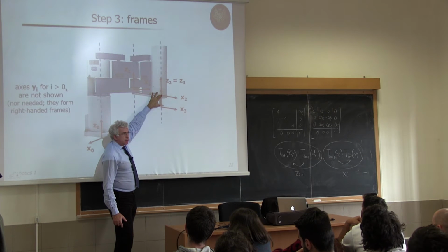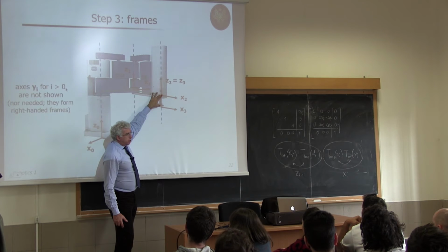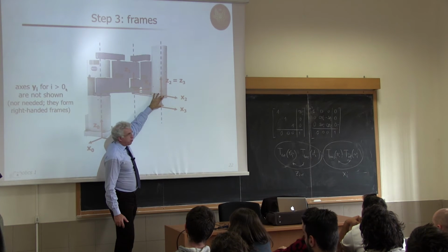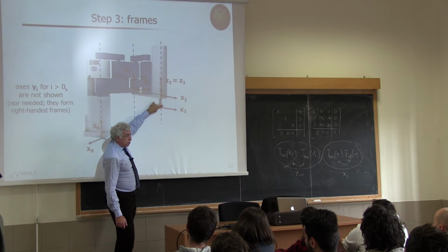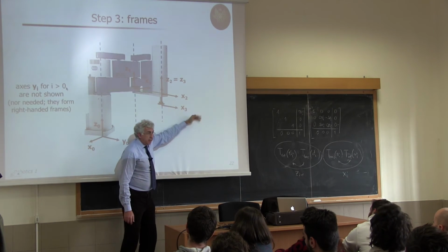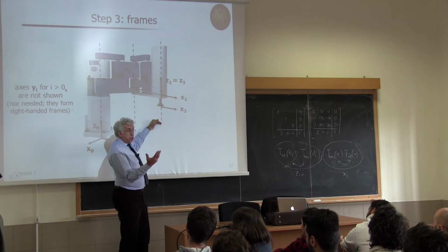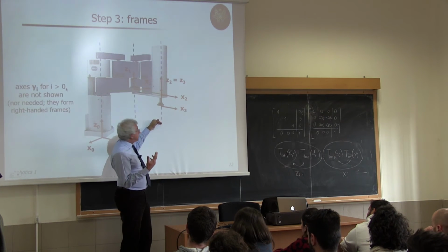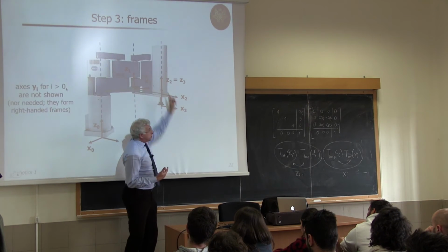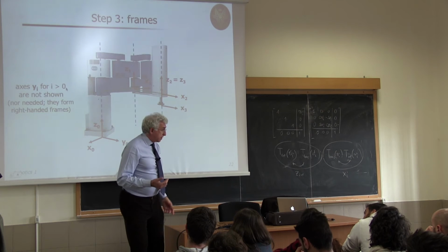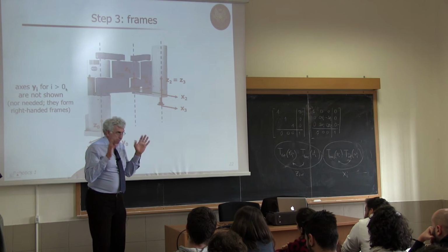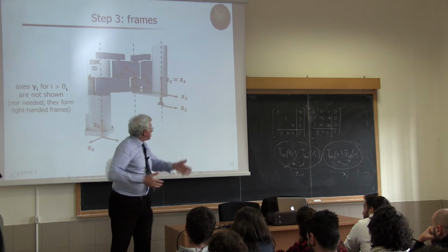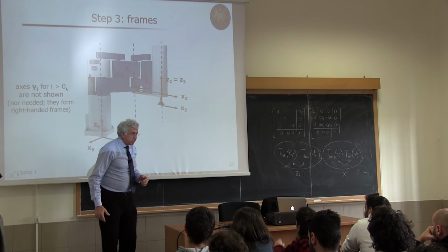It depends on which frame we want to make. No, it does not depend on anything. You already have the frame, so now you should tell it. It's negative, because you're going from this origin to this origin. You don't need to do a displacement A. You need only to do a displacement D, which is a variable, and it's variable D3 because it's joint 3, and you're going from here to there in the opposite direction of the joint axis. So this is D3, not minus D3, it's D3 equal minus 10 centimeters. Okay?